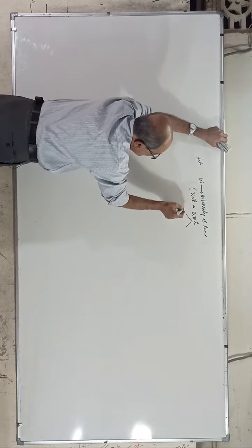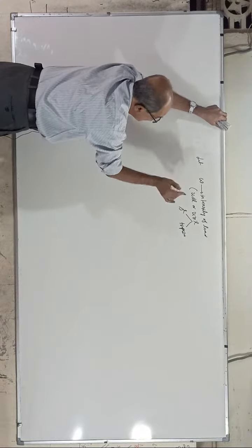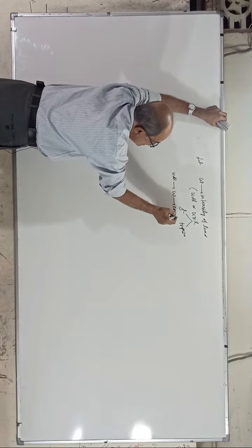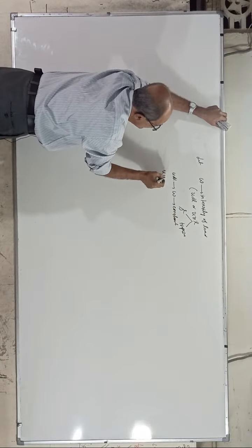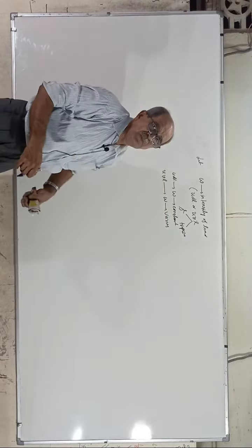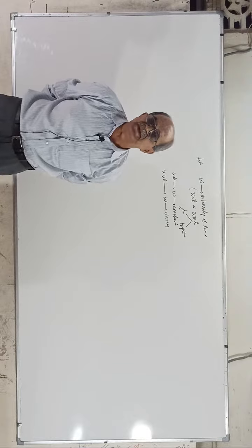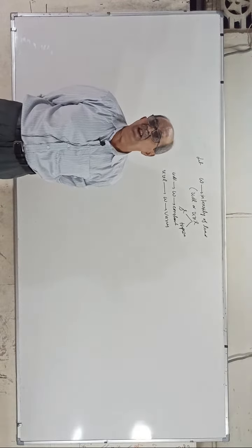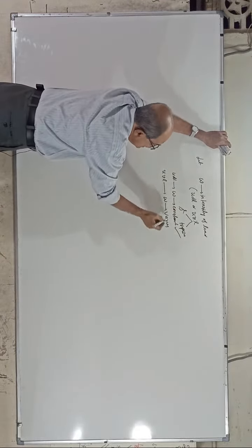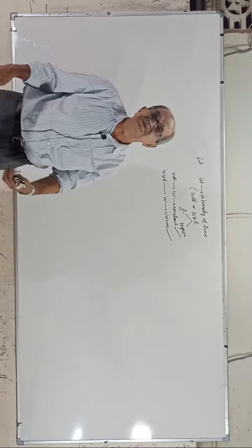In UVL, either triangle shape or trapezoidal shape, anything. Remember, if it is UDL, then intensity is constant. If it is UVL, then intensity w varies. That is the name, uniformly varying load, UVL. So anybody can make out: UDL is represented by a rectangle, constant; UVL by a triangle or trapezium, so there is variation. UDL intensity is constant, UVL intensity varies, so it is not constant.